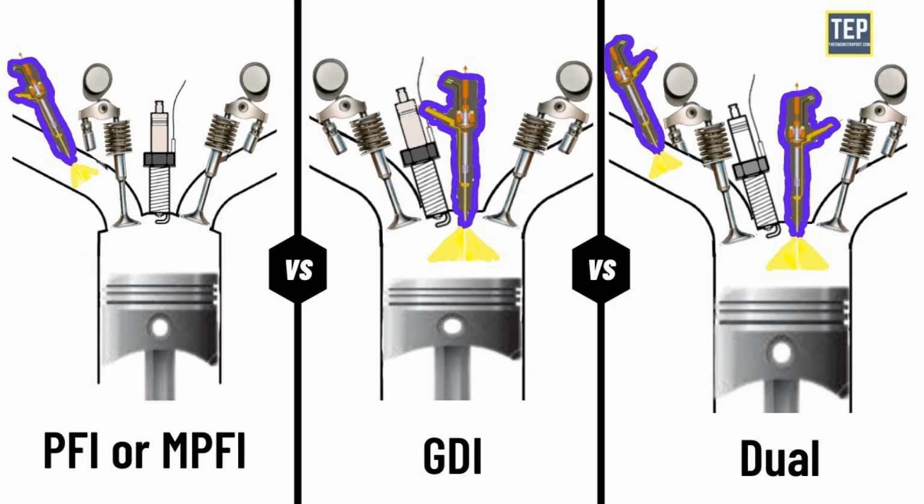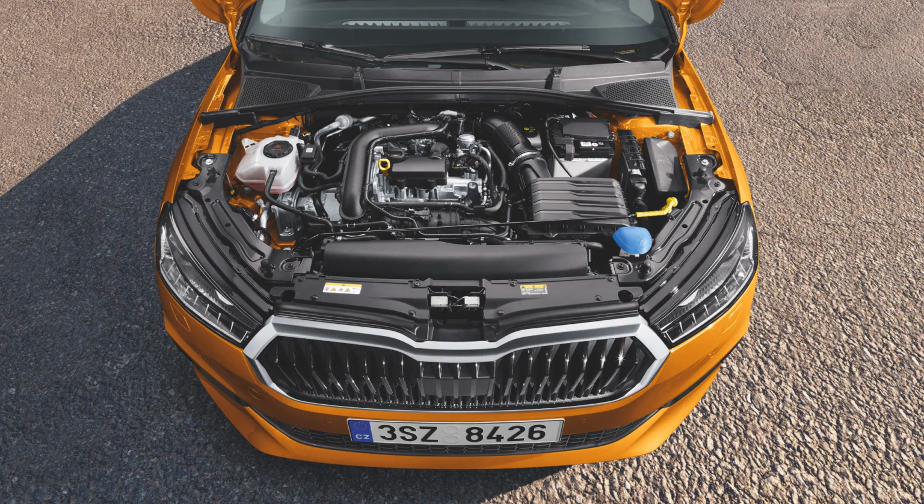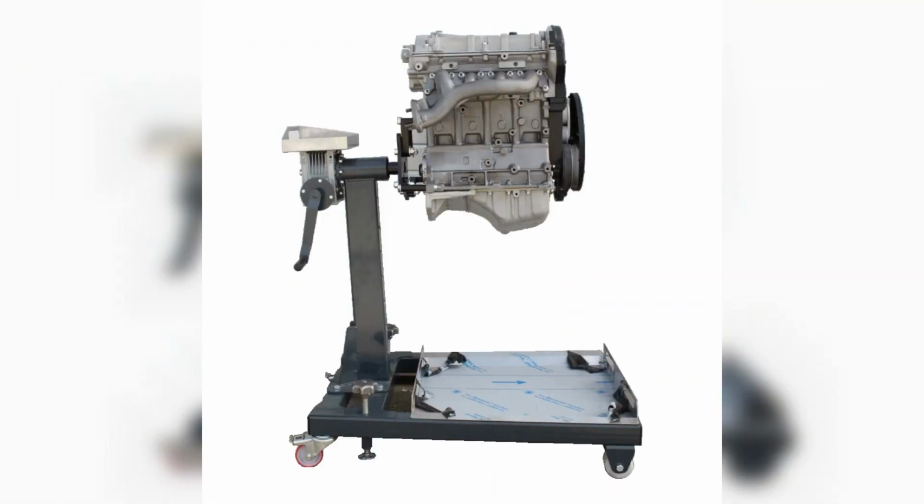Advantages of engines with MPI injection: precise fuel-to-air ratio. Gasoline is injected by nozzles into the intake valves of each cylinder, so uneven filling is eliminated. The injection moment is determined by the control pulse applied to the injectors. The amount of fuel supplied depends on how long the injector has been open. The MPI engine power system is controlled by the ECU, which calculates the injection moment and the amount of gasoline based on the readings of the sensor equipment.